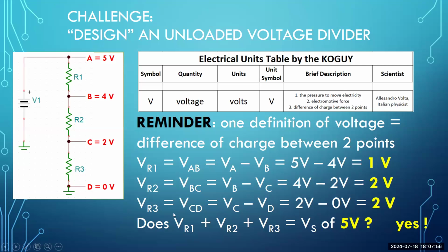So here's a double check for you. In a much earlier training video, we discussed series circuits. And what do you remember of one of the rules of series circuits? In series circuits, the voltage across R1 added to the voltage across R2, added to the voltage across R3 in series must add up to the voltage source.